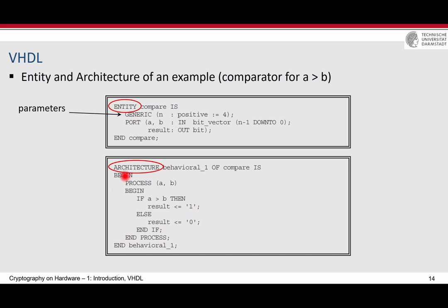And you should keep in your mind, this is not something which is done sequentially. This is just a way to write the functionality of a hardware. And the synthesizer will understand this and will turn this into a combinational circuit. This is super important. You should not think that this is checked, and the next clock cycle this, and the next clock cycle this, and then this is done. There is no clock cycle at all. This is just the way of representing the functionality of the hardware.